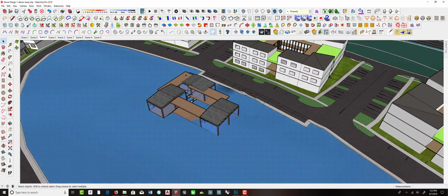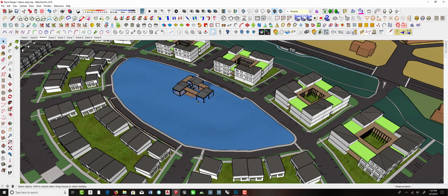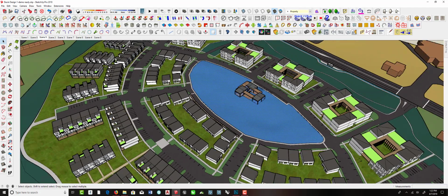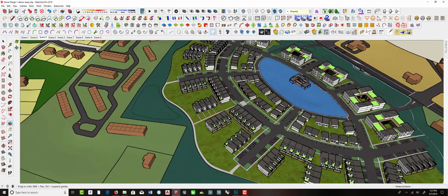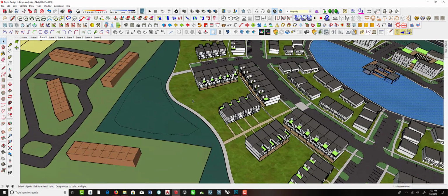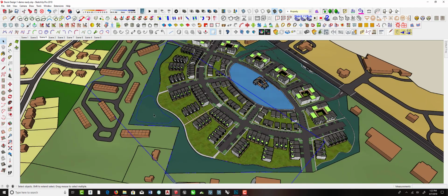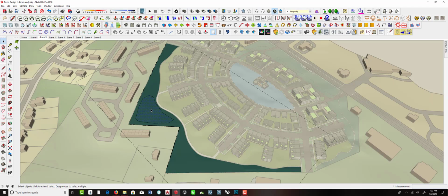So what we want is this one area to be free of any of those other divisions, because now that you have a new and more detailed design, we want to be able to go through and place surfaces and structures within this and regrade this to match the new design that you're working with. Now, in this case, as I said, it works out really nicely because this is already cut off from the rest of the model by virtue of its position between the roadways. If you had another area that you wanted to work on, and I had worked through this a little bit previously, there's a way to subdivide this that's really quick and easy.